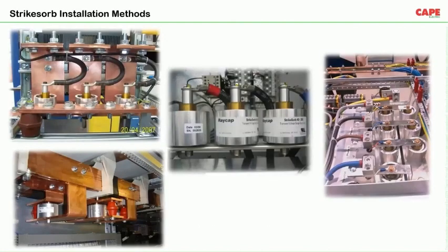These are the various connection examples of how bus bar mounted SPDs are connected. Normally, you can make a separate earth bus bar for connection of these SPDs, and you can also connect them on the phase bus bar. With this type of connection, since it is connected on the bus bar, wire length is 0, or very, very short. Only a small wire length of, let's say, 10 mm is required just to connect the SPD with the body of the panel, which is again connected to earth. So with this kind of SPD, we can make wire length very minimal, almost 0.